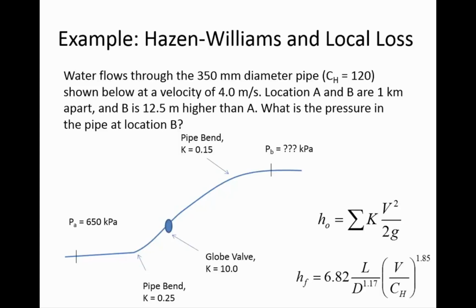What I hope you remember from the lab last semester is that laminar flow in a pipe is actually very rare. It's not very common that the water is moving slow enough for conditions to be laminar. So it's so unusual for you to have laminar flow that 2.0 isn't going to happen very much when you're applying the energy equation.